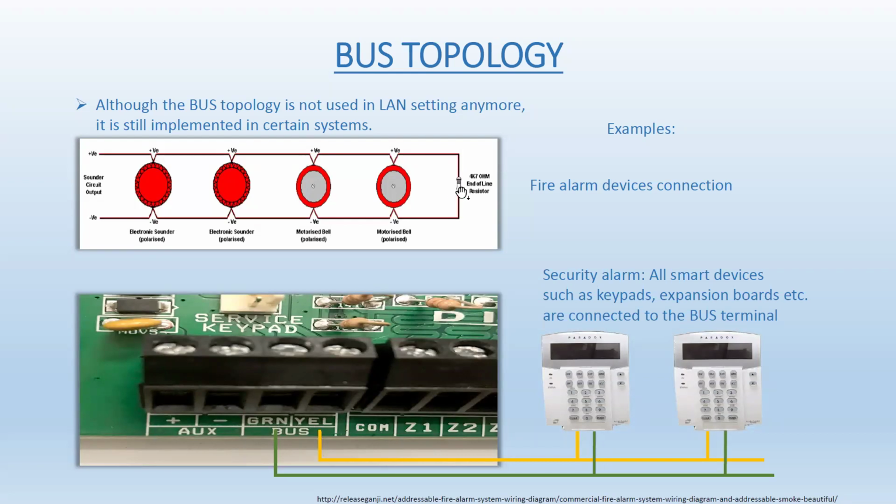If the resistor is broken, if that thing is disconnected, then the zone is going to see an open line. Is it going to trigger into alarm? No, it is going to trigger into a trouble mode, and it's going to produce annoying beeps at the panel, so the people in the office are going to investigate why this thing is beeping. And when it's beeping, usually there will be a phone number to call right by the light flashing where this thing is beeping. It says alarm trouble, call so-and-so.